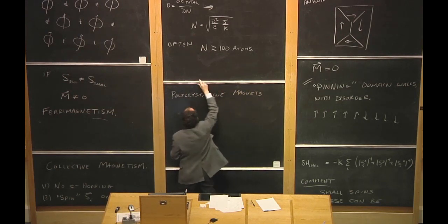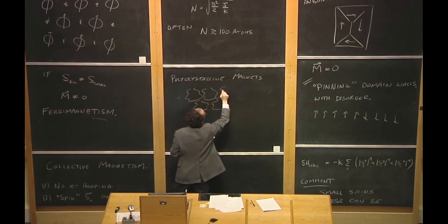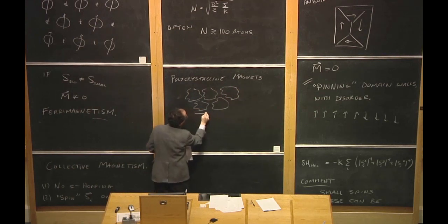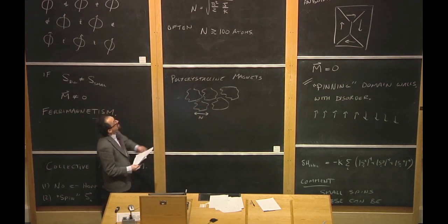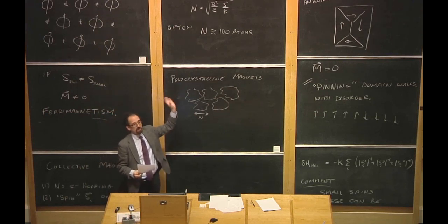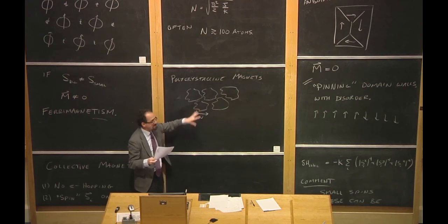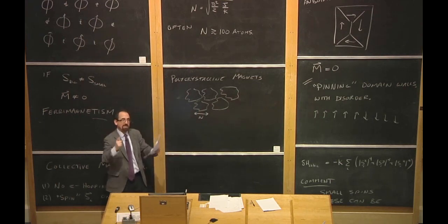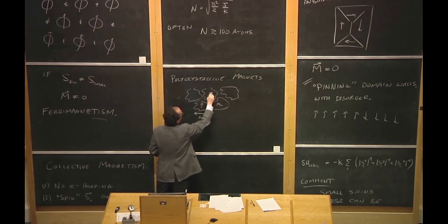So now we're talking about lots of little crystallites of magnetic material separated from each other. And if the size of the crystallite in number of atoms going across is less than this magic number, the size of the domain wall, then the whole crystallite has to have its magnetization pointing in just one direction.